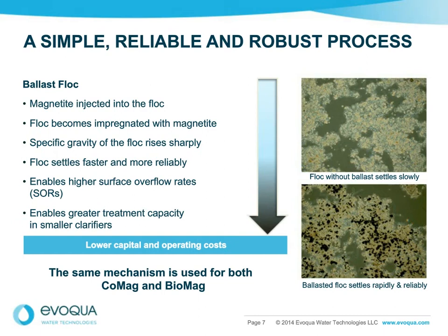They go on to a high-rate clarification step to get the solids to settle out, which allows you to typically run at much higher surface overflow rates or solids loading rates on clarifiers than you conventionally would, increase the treatment capacity of existing clarifiers, or give you enhanced effluent quality. And typically, because it's a reduced footprint versus other alternative solutions to overcome your treatment or process water challenges, it's typically lower capital and O&M operating costs versus other conventional methodologies, which may be large clarification or filtration steps.